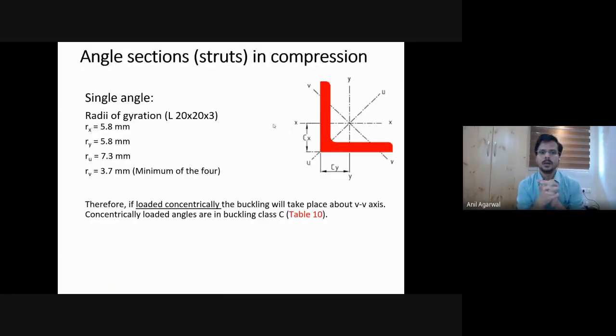Okay. Moving forward, so I had talked about flexural buckling before, and I had kind of alluded to this idea that flexural torsional buckling also exists for members, especially for the members which are asymmetric, right? But I had said that angles like what is shown here, even if it's an equal legged angle, the two legs are equal, it has one flexural mode of buckling, that is about VV. This is a singly symmetric cross section, right? So about VV, that is the smaller or weaker axis, the axis that is not of symmetry. About this axis, you have flexural buckling possibility.